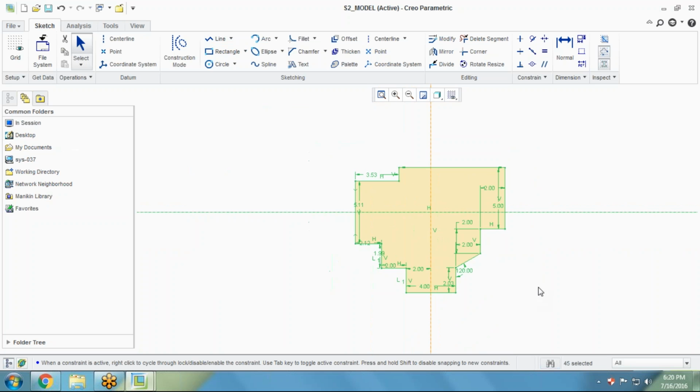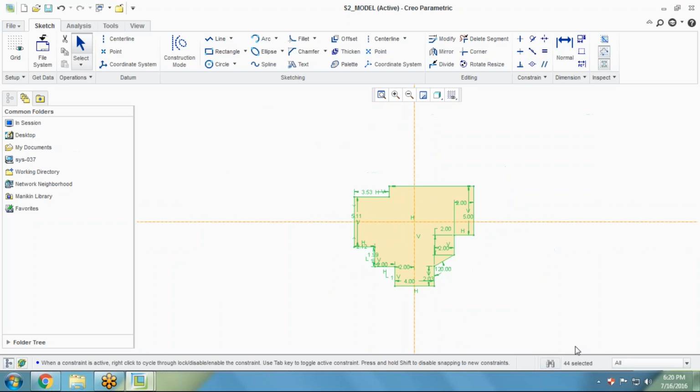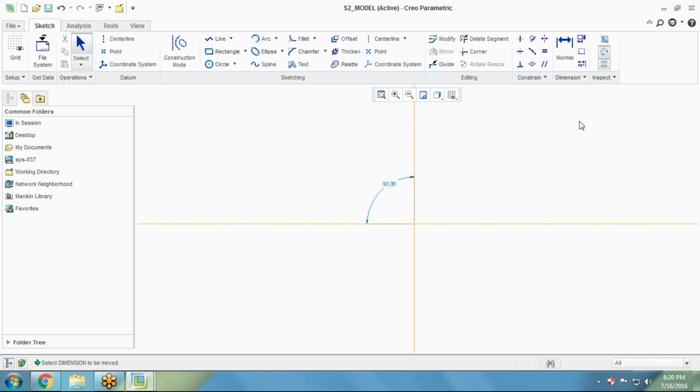After that I'm just deleting each and every section but the center lines. So you will see there, if I want to show some constraints over there, you can see the line is not constrained now. So I'm just giving the value, and this is a constraint section. So here one is vertical, second is horizontal. So I'm just defining one which is vertical, second is horizontal. So you'll see the constraint we can define also after creating the object. So that is called post constraining. And initially when we are working and the constraint comes automatically, that is called pre-constraining.